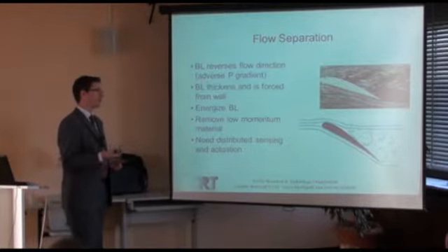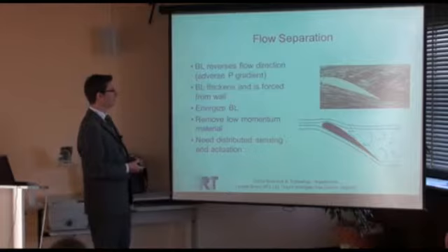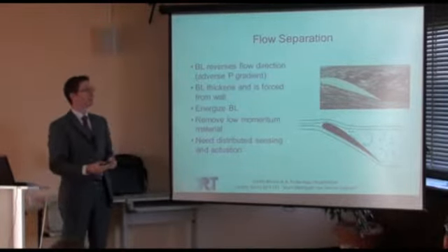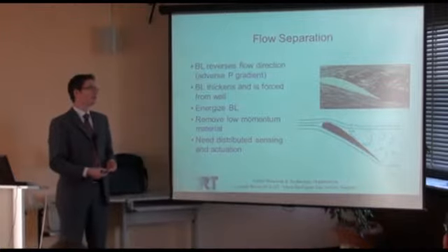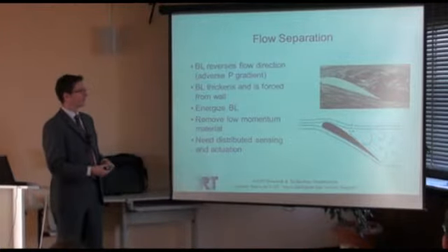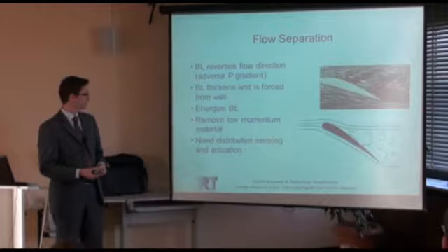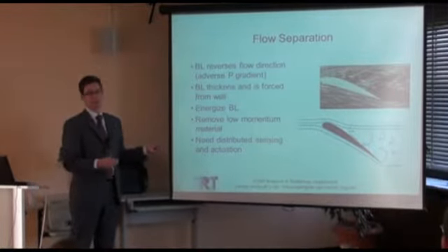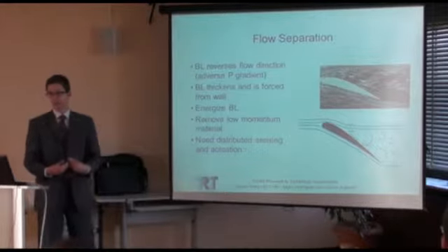Now if you think of actuation, you've got the possibility to energize the boundary layer, to put momentum into it, to put energy into it, and therefore energize a low momentum fluid. Another technique would be to remove this low momentum material, so you suck it away, basically.